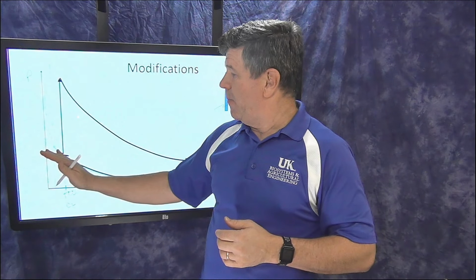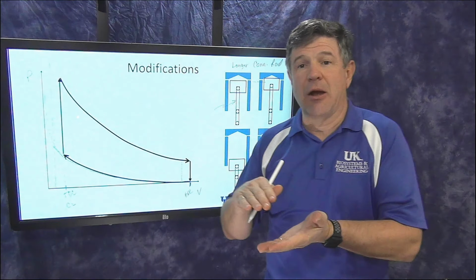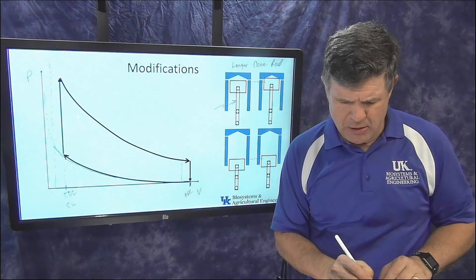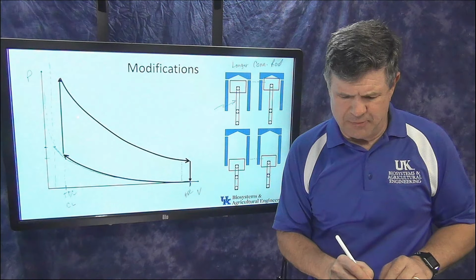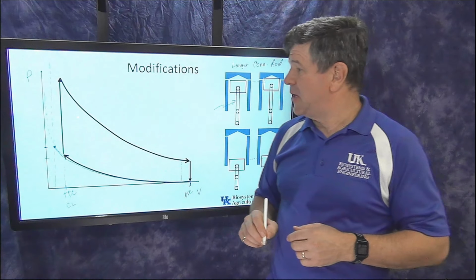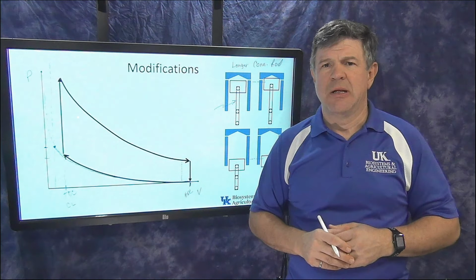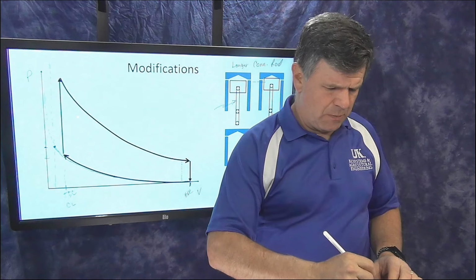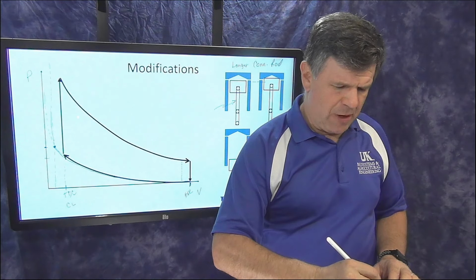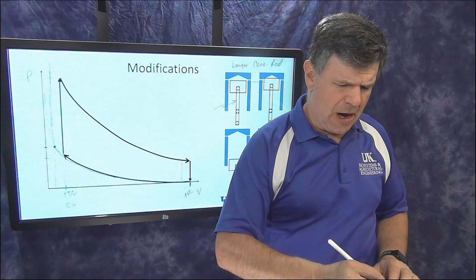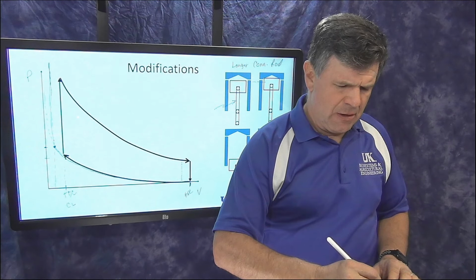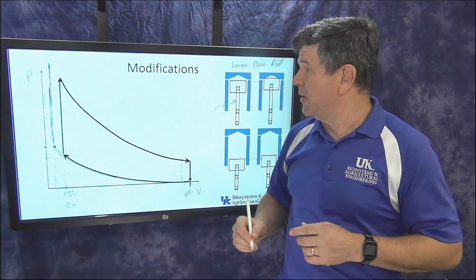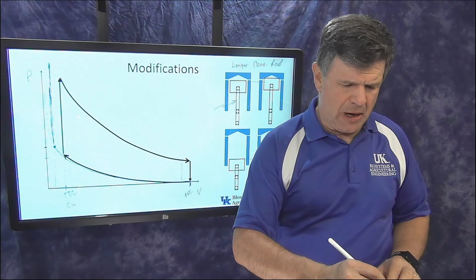So what has happened here, man, I brought this up to a lot higher pressure. So that's a pretty significant jump in pressure. So I was here before, now I hit that top dead center at a much higher pressure. So it was a big pressure increase. Well, now what happens when I ignite this fuel, I get my big pressure jump. Boom. And because I started higher, that pressure jump is going to go quite a bit higher than what it was before. So that pressure jump is going to go up something like that. It's going to go up really, really high.